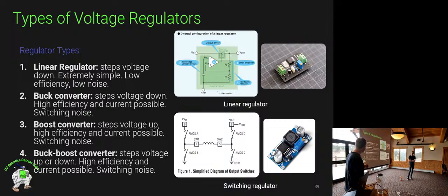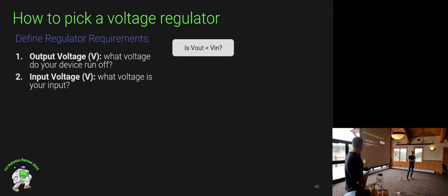And these switching systems, the thing to remember: super efficient, noisier. When I say noisy, that's electronic noise, not audible noise. They do generate some audible noise, but they're very much noisy in terms of, if you were to measure with an oscilloscope, you'll see a little more ripple. The control system that controls it just isn't as tight as a linear regulator.